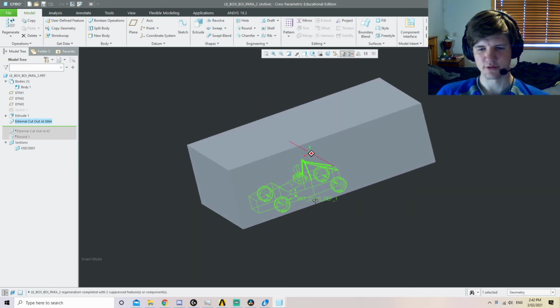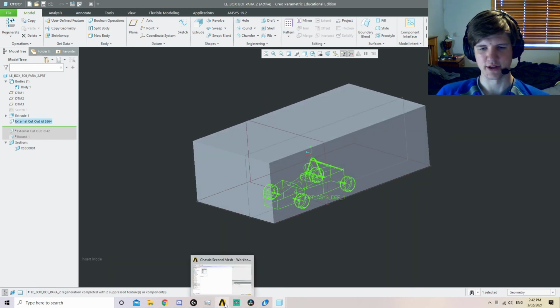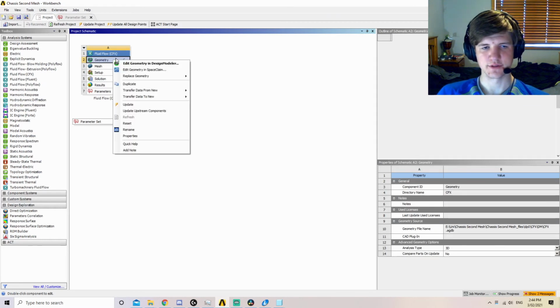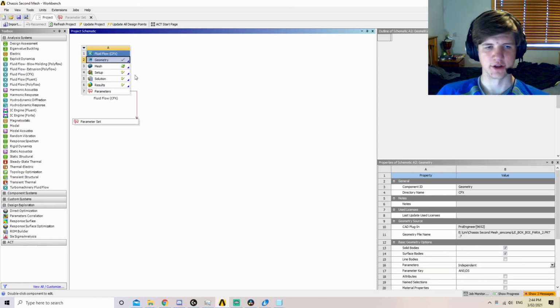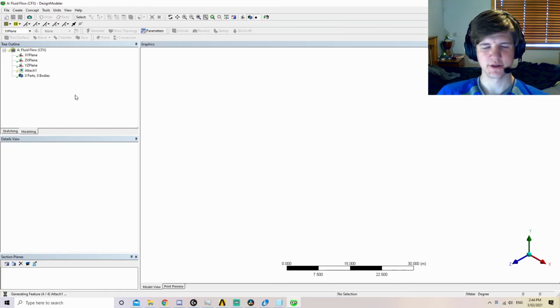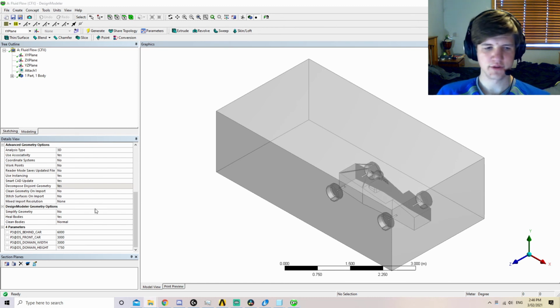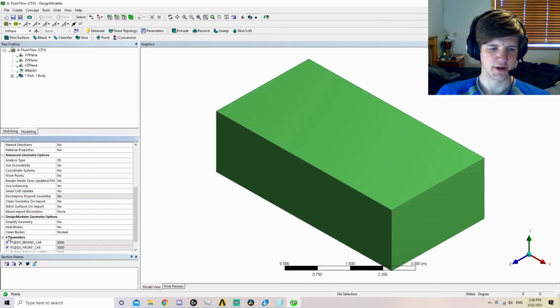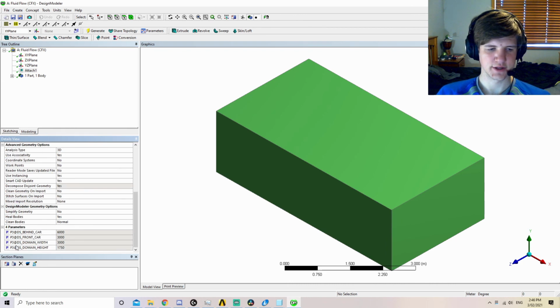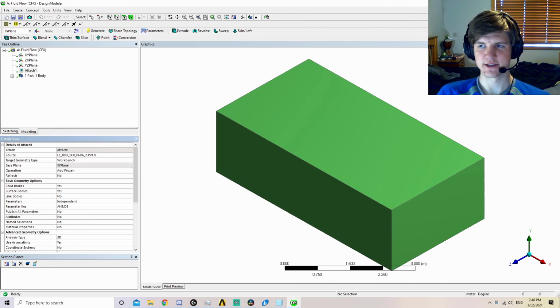Now we have some geometry in Creo, we import it into ANSYS. To import geometry, we simply select the geometry that we would like and then right-click and edit in Design Modeler. Select the Generate button to attach the geometry, and once this is complete, we can view the geometry. To enable parameters, scroll down to the bottom of the geometry selection in Attach 1 and select the checkbox for parameters. These parameters can now be changed in ANSYS, as seen here.